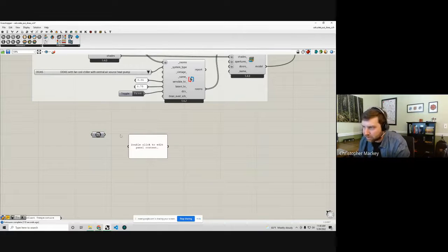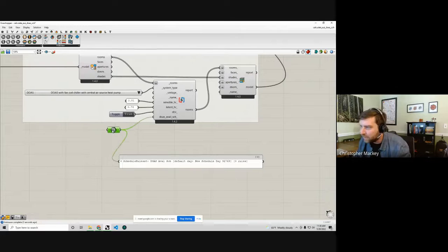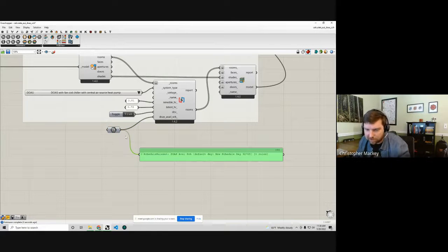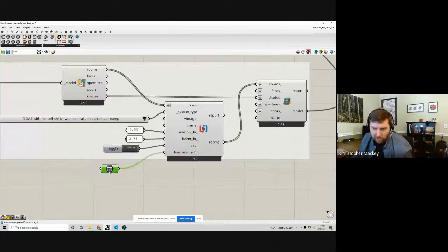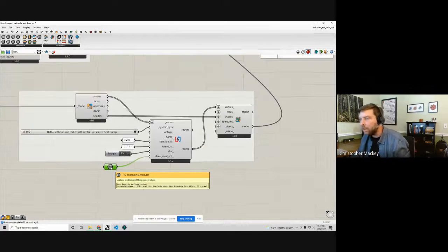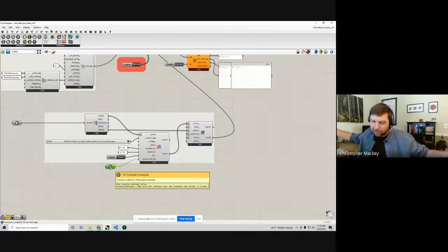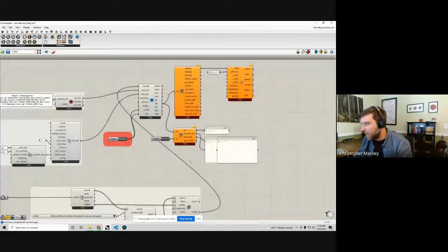And you'll see that now, instead of having to use those clunky Grasshopper components, I actually get a schedule object that I can then apply to this DOAS availability right here. This is the same exact type of schedule object that you get out of those components. It makes it a lot easier to build and manage these schedules. And in case you're wondering, the schedule will be here the next time you open up the Grasshopper definition. It's embedded within this parameter component. So you can really easily build up a Grasshopper definition with all your schedules using that, and then edit them this way.